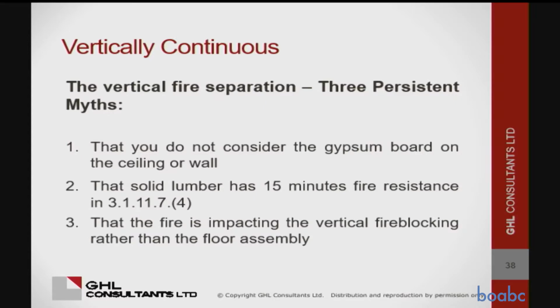So, I mean, I don't know why you couldn't. When I first started at the city of Nanaimo, we would look at this and say, okay, there's gypsum board on the ceiling, that has some rating, and then there's this block, and that has some rating. And then there's also this in 3.1.1.1, on the section on fire blocking, it says anything that will stay in place under the fire test for 15 minutes can be used as a fire block.